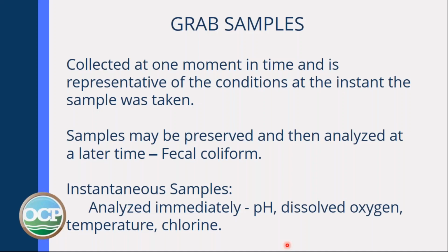Grab samples can be preserved, and fecal coliforms are a really good example of how you would take a grab sample, cool it down, and then analyze it within a certain number of hours.